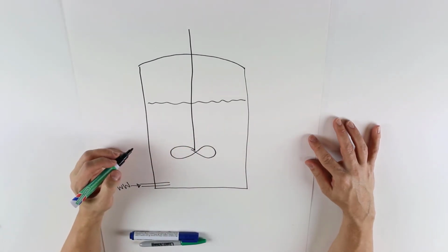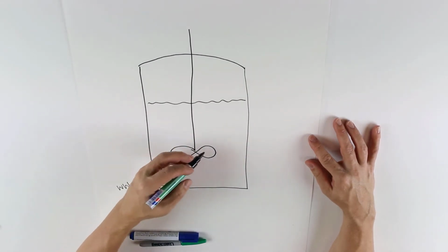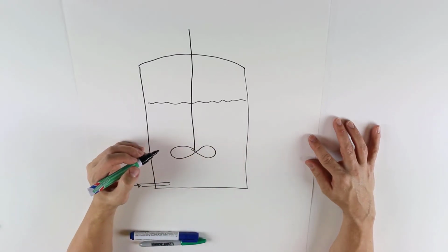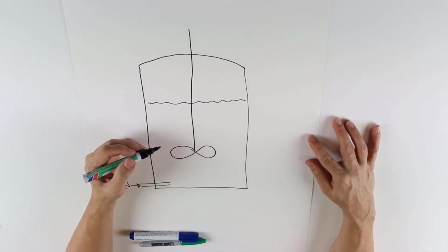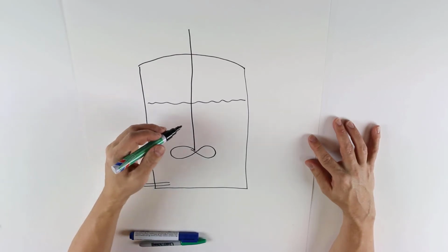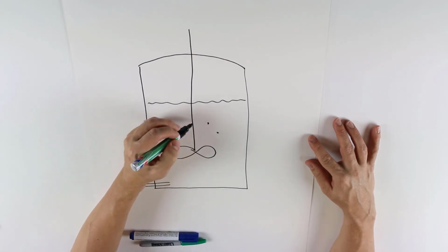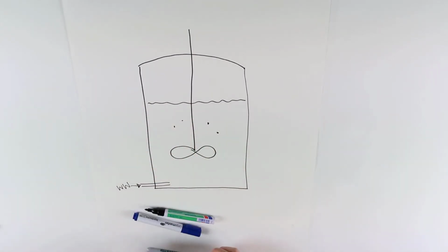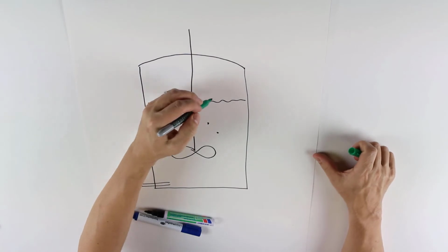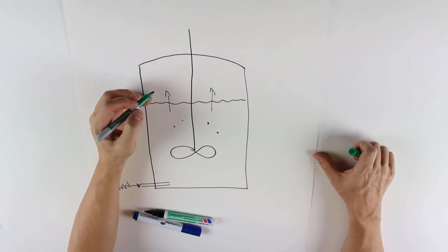This is just for illustration. Typically the stirrers can be on the side and they're put there in a way that you have adequate mixing of the reactor. These types of reactors are very suitable for sludges, anything that is quite viscous. The gas that is being produced moves nicely to the top and is collected there.